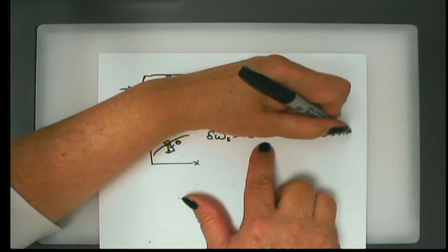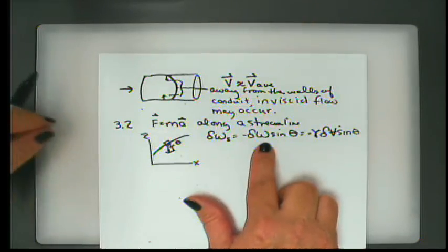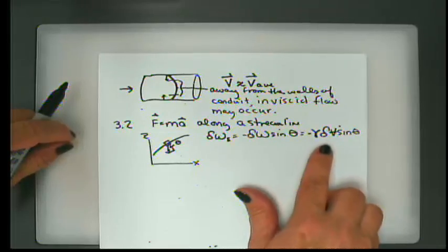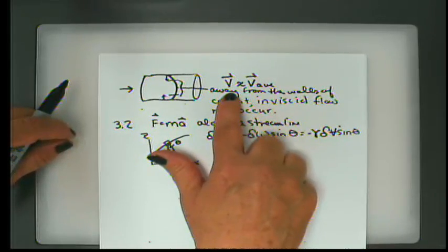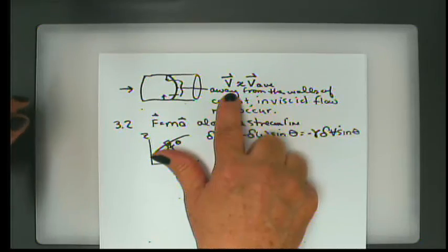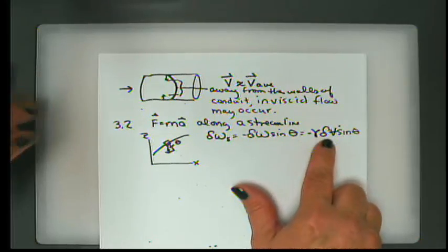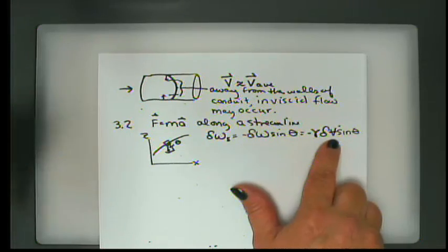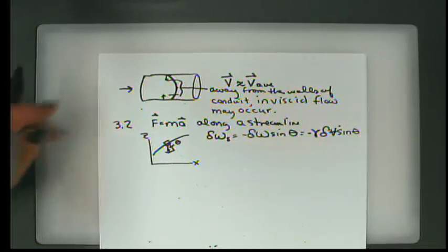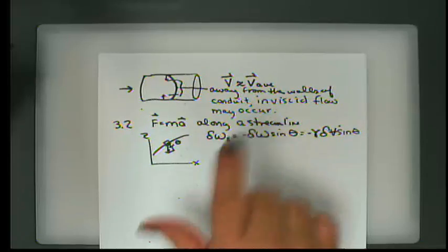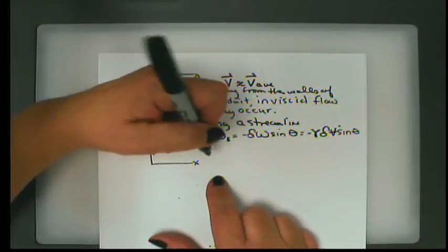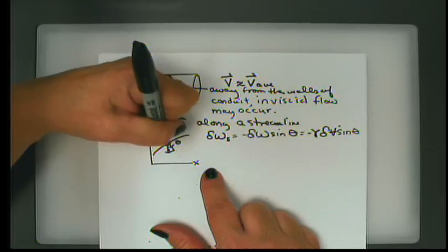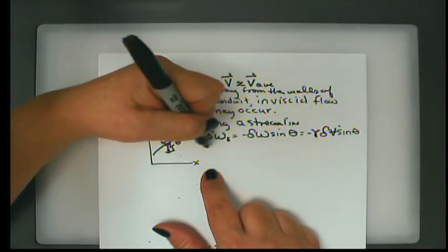Okay, and once again, times the sine of theta. Right. Now it's important to note, we've gone over this before, but velocity, which I represent with an arrow over it, your book just uses a straight V, or volume, even though they're both V's, are very different. So your authors use a slash through the V in order to differentiate it from velocity. We also have a pressure differential from this side to this side,